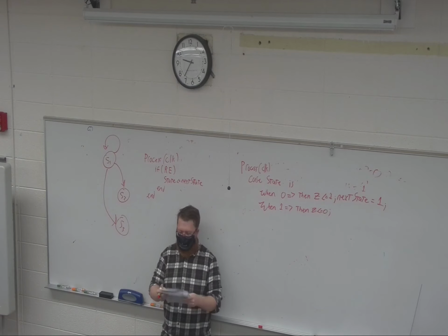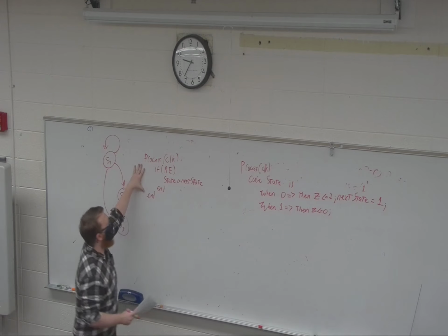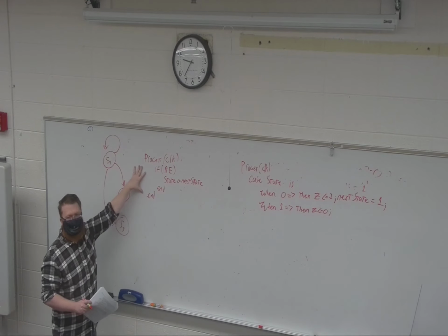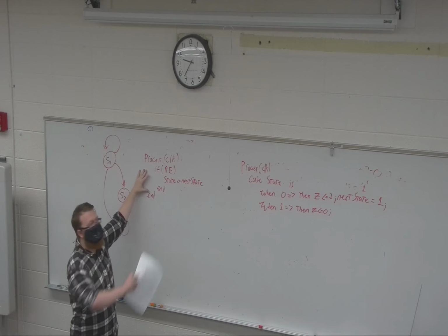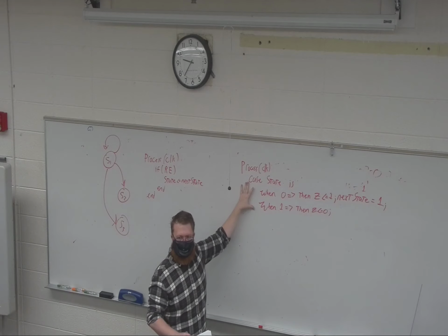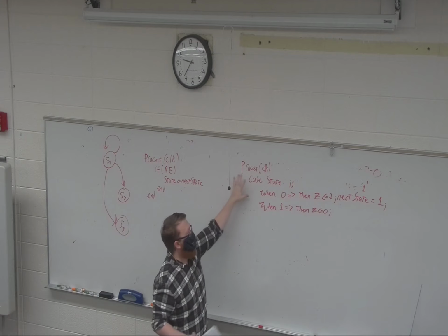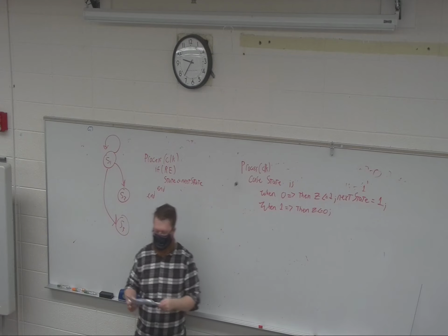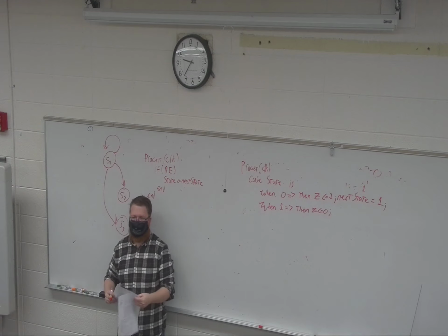This will walk you through a whole state machine on it, but just remember the easy way of doing it: have a process that's always updating the state based on whatever the next state is, and then have another process that is the logic within those states for making those decisions. And you can have the whole state machine within the case statement. And you will do exactly that in Lab 1, probably.